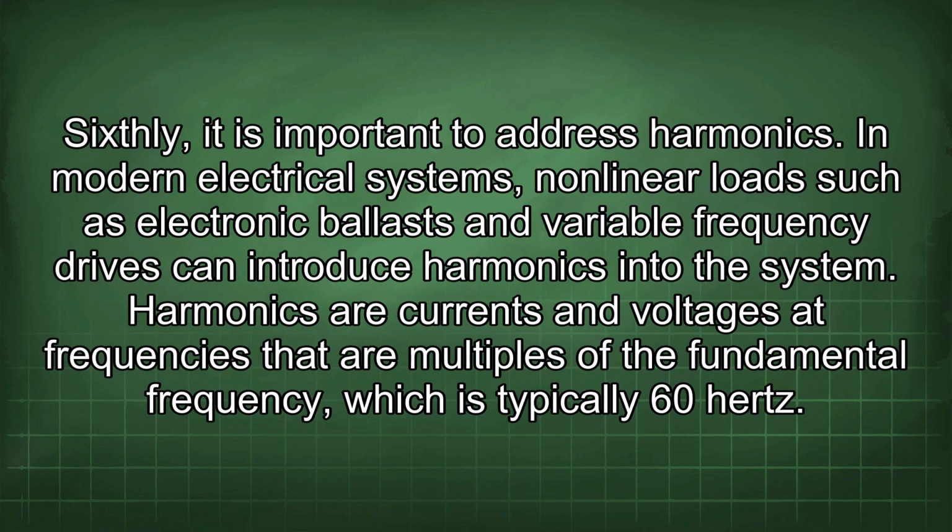Sixthly, it is important to address harmonics. In modern electrical systems, nonlinear loads such as electronic ballasts and variable frequency drives can introduce harmonics into the system. Harmonics are currents and voltages at frequencies that are multiples of the fundamental frequency, which is typically 60 Hz.